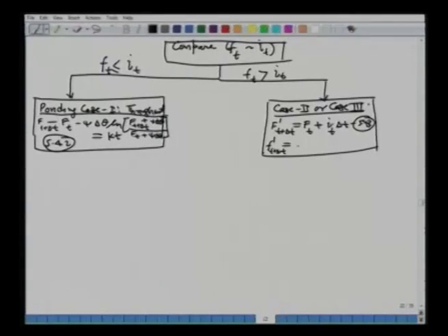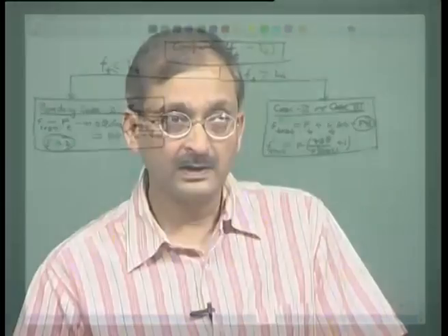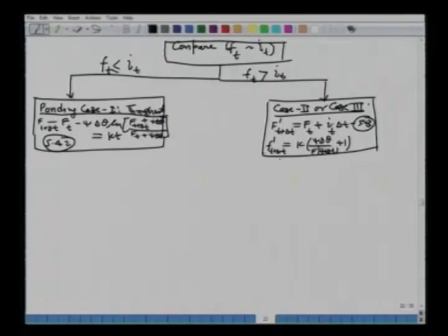So, this would be nothing but equal to K times psi delta theta over capital F prime of t plus delta t, which we have just found out, plus 1. This is the basic equation of the Green-Ampt. So, we have the rate of infiltration at the end of the time interval. Now, we compare this with the rainfall intensity at the end of the time interval, which is the same as I t, because we said during an interval rainfall intensity is constant.